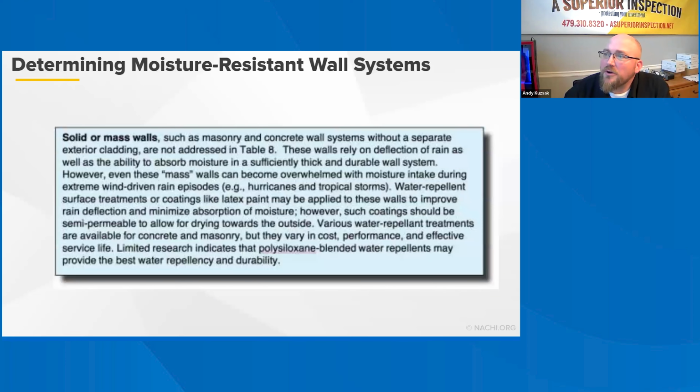If an exterior water repellent coating to masonry is apparent, pay close attention to the face of the product to make sure that spalling is not occurring. Often the wrong product has been applied and is not permeable, causing water to be trapped inside, and the face of the masonry will spall due to capillary action causing hydrostatic pressure, thermal expansion, and/or osmotic pressures.